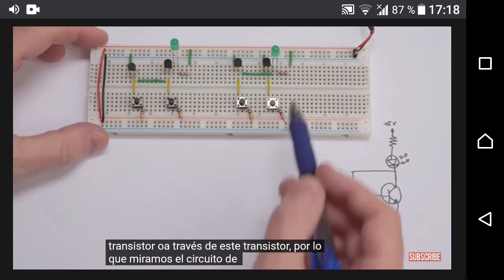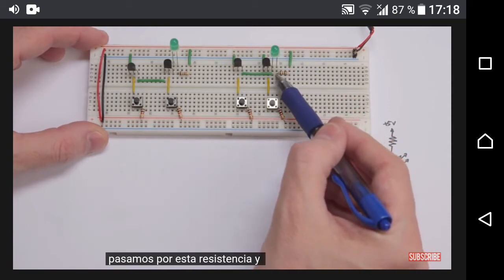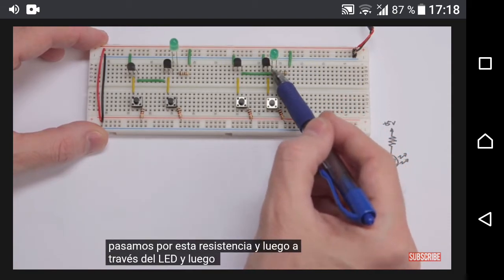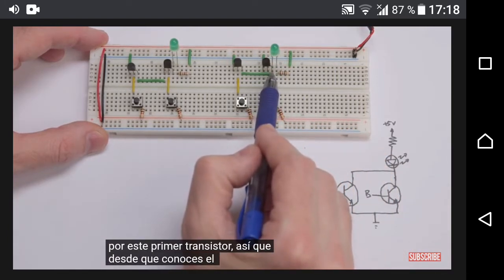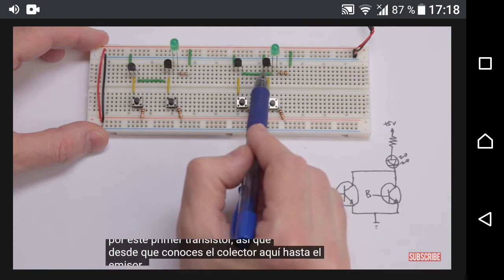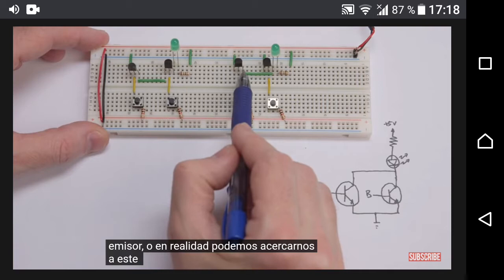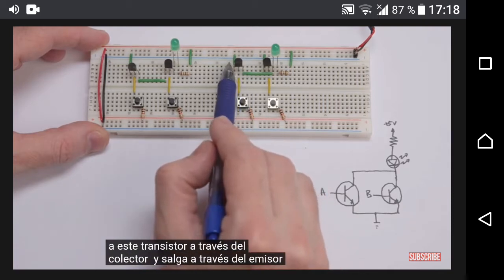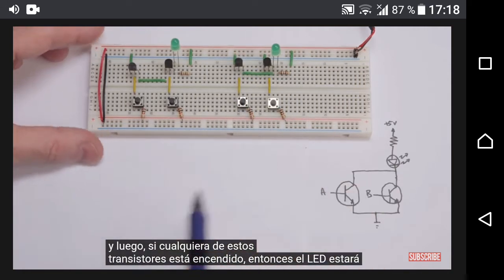So if we look at the circuit closely here, we can see that from the positive rail, we come through this resistor and then through the LED, and then we can go through this first transistor, from the collector here to the emitter, or we can come over to this transistor through the collector and out through the emitter. And so if either of these transistors is on, then the LED will be on. So we can test that out.